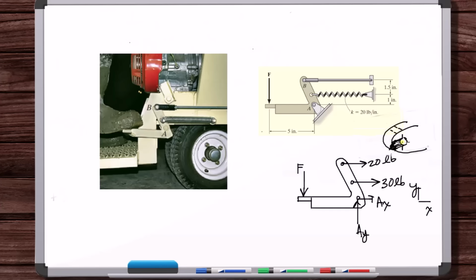In other words, the force from the pin on the inside face of the link is higher towards the center line of the circle, and then it tapers off as you go away from being in line with the center of the circle.